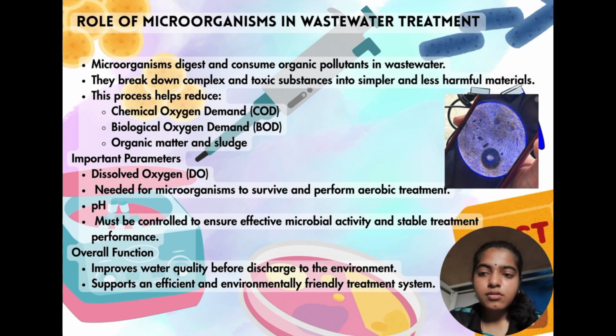Next, I will explain the role of microorganisms in wastewater treatment. Microorganisms are the key component of biological wastewater treatment because they digest and consume organic pollutants in wastewater, where they break down complex and toxic substances into simpler and less harmful materials. Through this process, the amount of organic matter in the wastewater is reduced, which helps lower the biological oxygen demand and chemical oxygen demand. The microorganisms also contribute to the reduction of sludge and improve the overall quality of treated water.